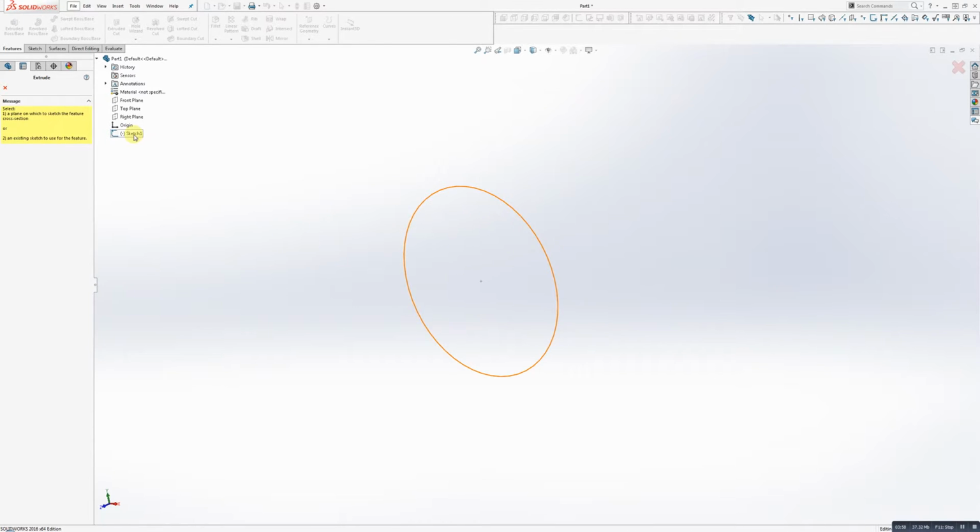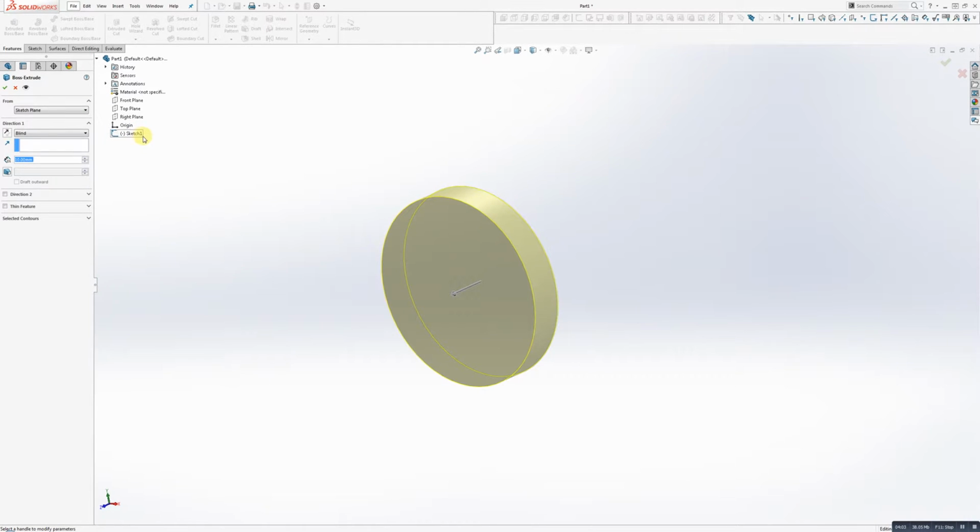So I'll click on it here in the design area to practice that, and it's the same procedure as before. Whereas before we were inside the sketch, and so SolidWorks automatically knows, okay, this is an active sketch, you're hitting the 3D tool, so I'm assuming you want that 3D tool to hit that sketch, so it just fires off from there. But when you're outside the sketch and then you activate it using the tool, this is that procedure here.